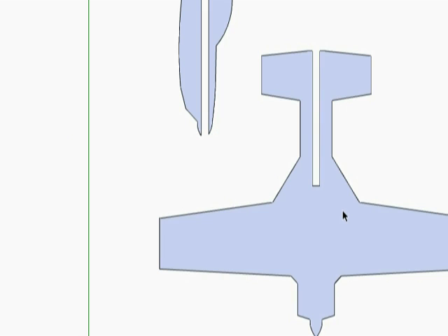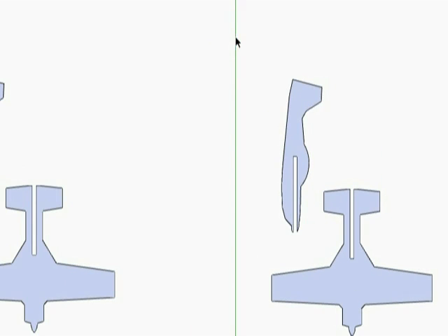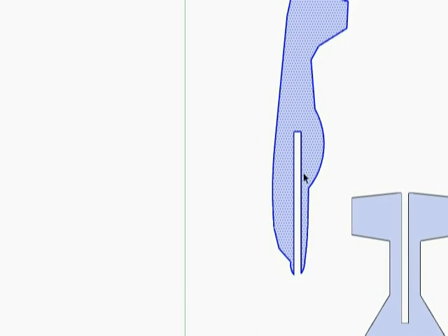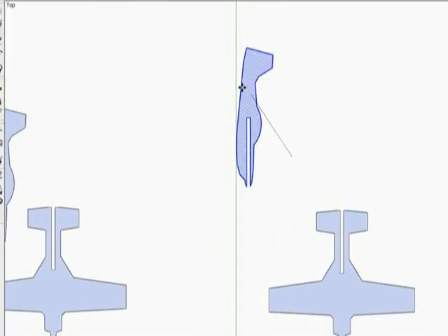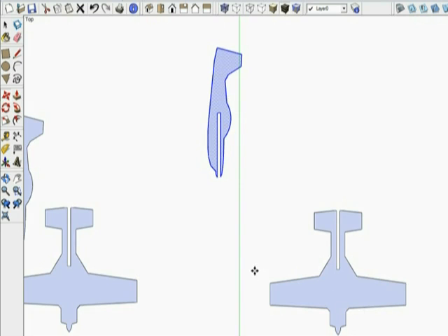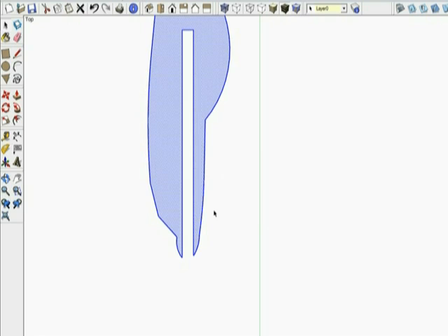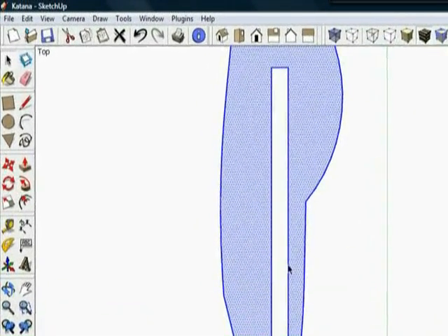And there's some things that we can also do. I'm going to go ahead and give these parts some separation so that I don't mistakenly select one or both of them, or elements of both, when I'm ready to use my move tool, when I'm ready to put it all together. Something that you can look at here as a rule of thumb, if we've got slots that we're going to line up and we start putting together a 3D model, I really like using my move tool.